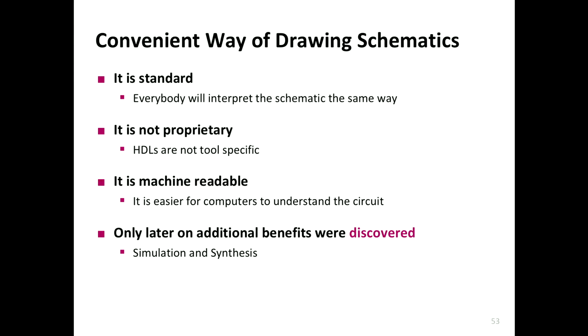There's a big difference between software development and hardware and chip design, because it takes approximately 6 to 8 months from your chip design to get back the actual chip. In software, you write code, you deploy it, you test, it doesn't work, and then you fix the bug. But here, the turnaround time is much longer, and imagine if every bug needs to be fixed in this way, you're not going to get any product out at all. So you can simulate, synthesize, and test your circuitry because of these hardware description languages.